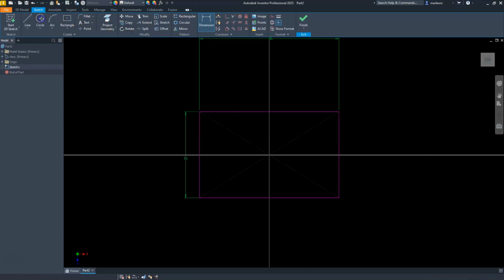Let's drop our circle on the inside of here, so I'll place a circle here. I'll take a look and see if horizontal, and I do get a horizontal line going. I'll select this center, and then the origin. Let's put a couple of dimensions on here, so a dimension from the center to the back here, and this has a dimension of 55. And then we'll need to type in whatever the diameter of this circle is, which will be 24.